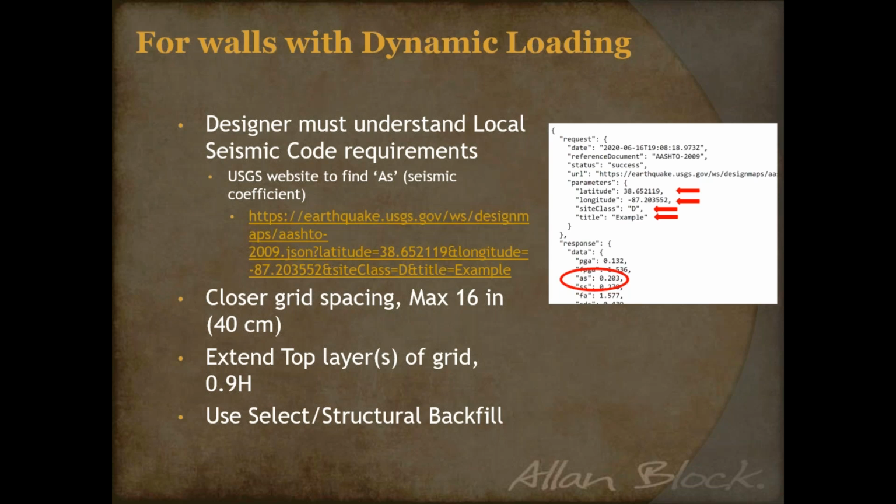Other thing that's in the best practices, yes, you need to understand the seismic design requirement, but look at the next couple recommendations that are in best practices. Closer grid spacing, 16-inch spacing, right? That's right out of our seismic testing. Extend the top layer geogrid. Boy, that sounds familiar too, right out of our seismic testing. And then we do like the idea of using selective structural backfill.